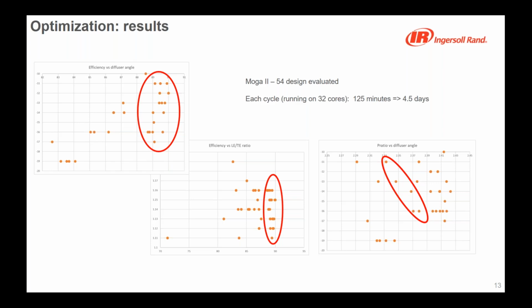What I did at that point, as I want to improve the efficiency of the machine, I went through modifying only the diffuser. And here is what I was saying before. You can segment your design. So the first step I did was to take the impeller diffuser geometry, coupled together, running together, but going to optimize at this point only the diffuser.